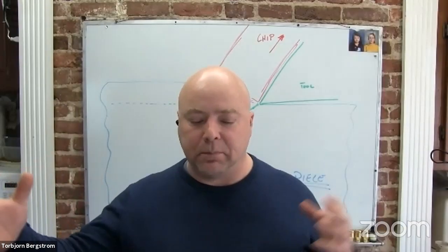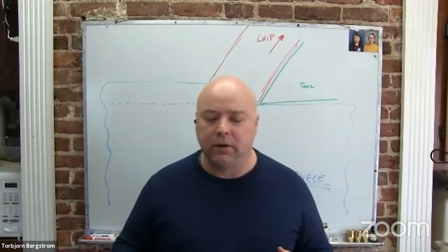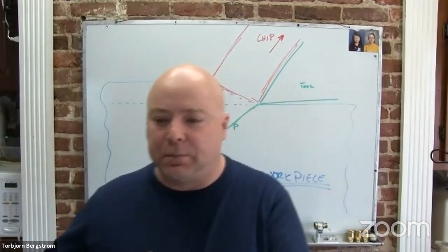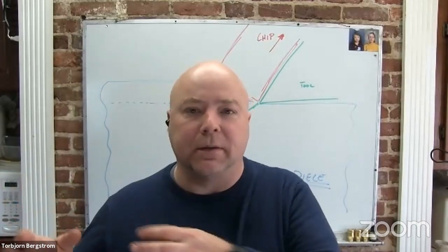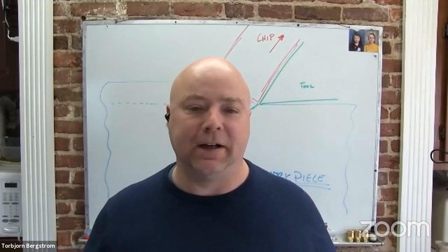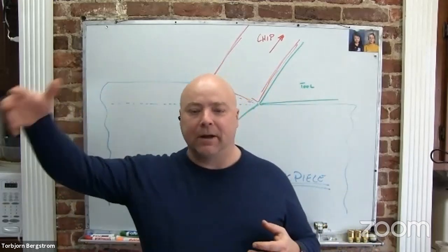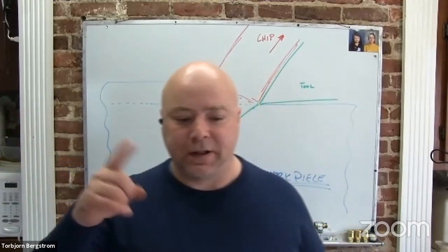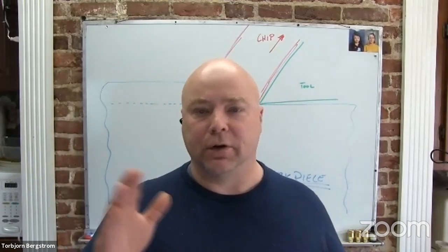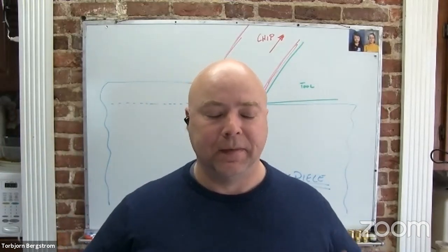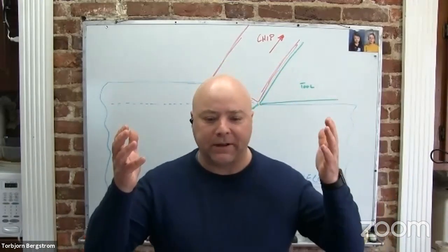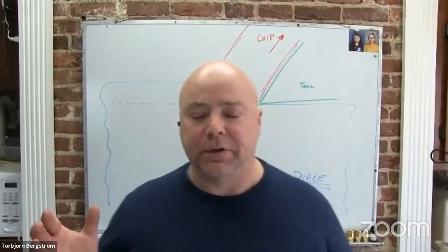You could use the equation we found yesterday, or you could look at the spindle load on the machine itself. Right. So you could measure the amperage and the voltage going to the motor that's causing the cut to happen. You don't have to just use the meter on the machine. You could get much more sophisticated measurement tools and data acquisition systems to accurately know the dynamic loads happening on there. Because what you see on the needle on the machine is pretty averaged over time, and it's intended to just give you a guide of how much of the machine's capacity you are using. But you could very accurately measure those things.